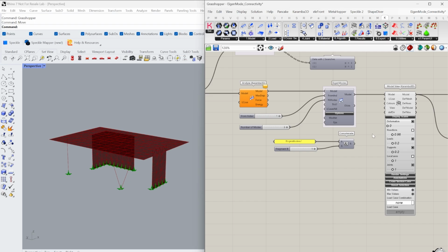For this reason, the value of the eigenmodes indicates how much force is needed to get the deflection represented by the eigenmode. Since a rigid body mode can be invoked with 0 force, the corresponding eigenvalue is 0 or nearly 0 due to numerical inaccuracy. We can view the values of the eigenmodes here.